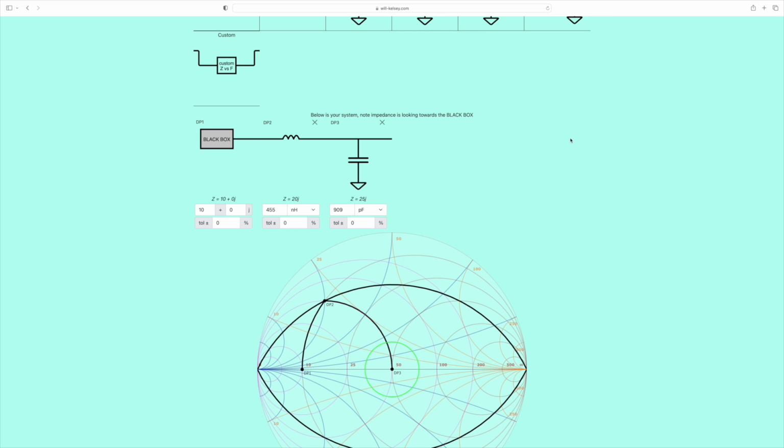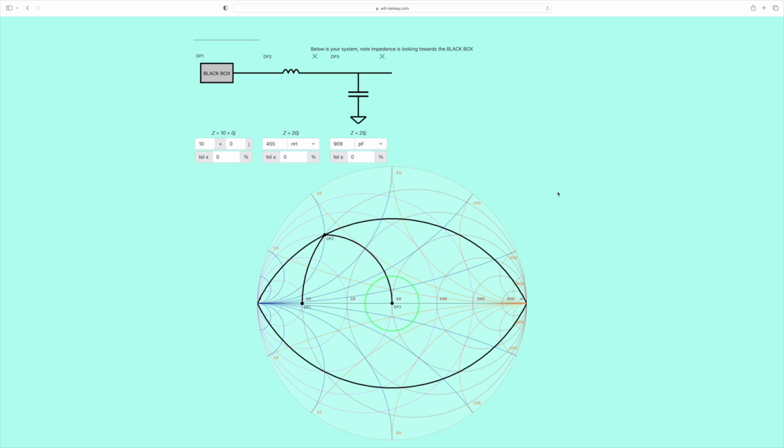Okay, so how can we cheat at matching complex impedances? Well, actually, I think this is where the cheating really comes in, and in a sense it's not really cheating, it's just more obvious what you're doing when you can see it. So let's take this example that we had of the low pass filter. But let's say we had an inductive reactance of 10 ohms.